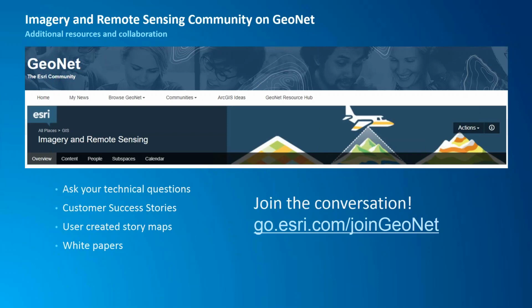Yeah, I might have answered Diego's question, but one suggestion I have is there's a GP tool called Tile LAS, and it'll take all of your LAS files and chop them up into smaller, more manageable sized files, and you can define the extent of the squares, so you can make them as big or small as you want. So that's a good tool to run if you have a really large single LAS file and it's taking longer to load into the software.